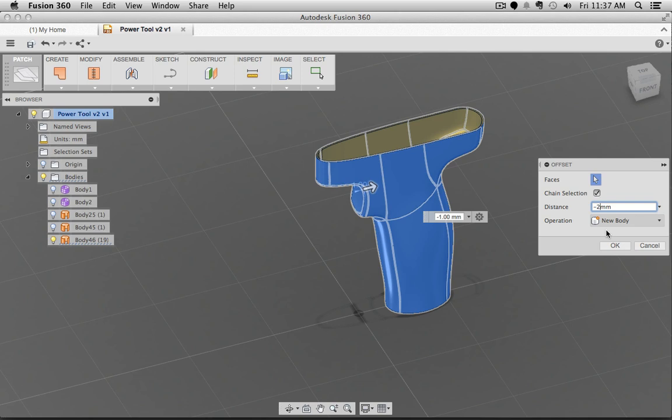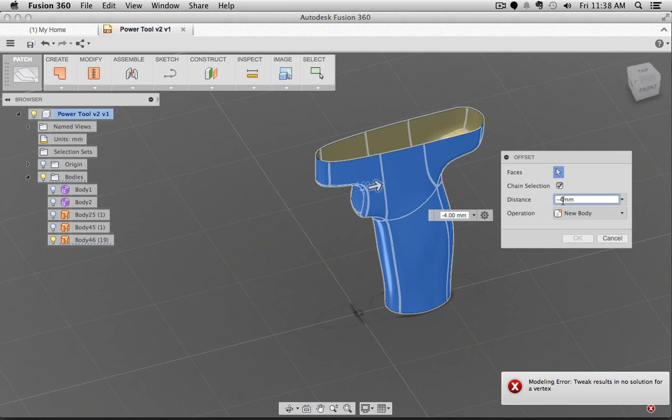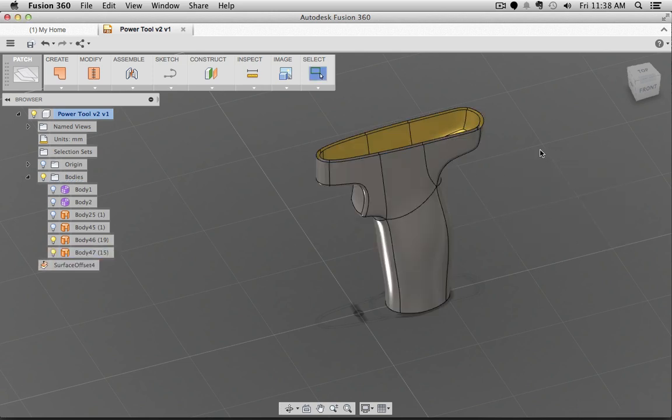And maybe for, oh, 2 actually was good. Okay. 4mm might be too big. Oh. You see, as simple as the shell is, there is actually a lot of math going on in the background right now. And yeah, there also I reached some configurations that are actually resulting in bad geometry. So the software will tell you that, nope, I'm not going to do this for you. But I think 2mm will work. Okay, perfect. Great. So let's take a look what we have.